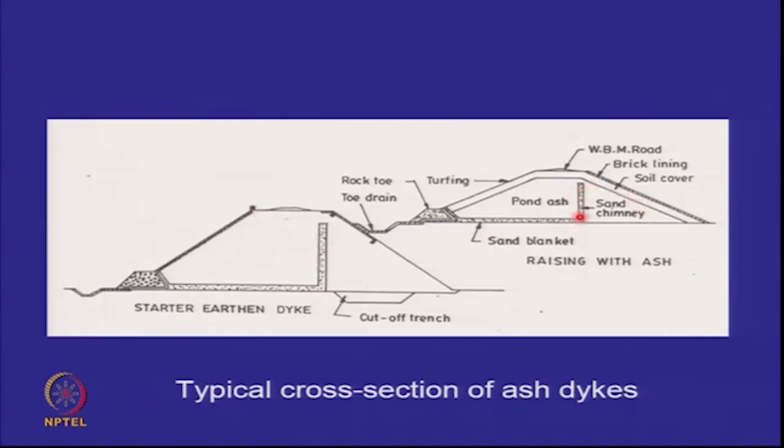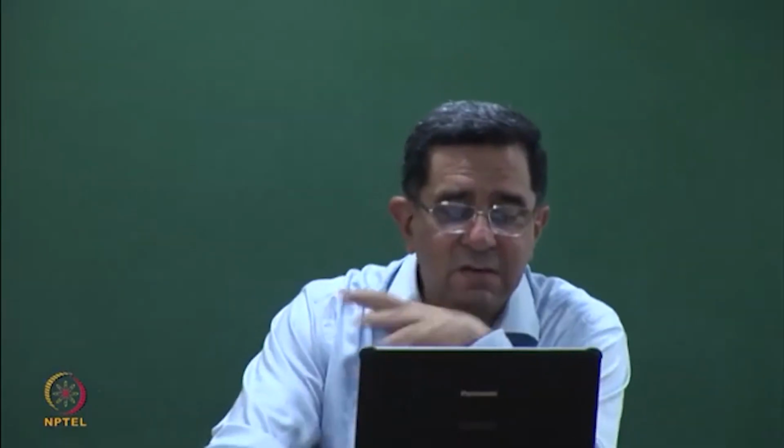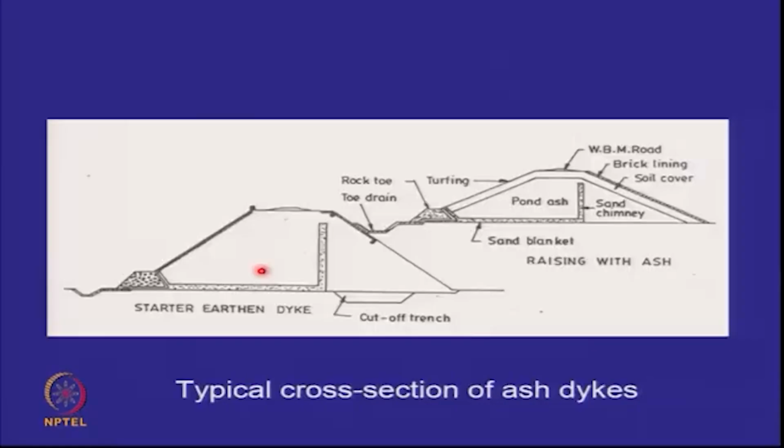And they are collecting the water of each stage in a toe drain and taking it away, right? So we are not allowing the water of this drain to come here, but if it overflows, it will come here. This water is collected in this drain, and in the lateral direction, the water is taken out by overflow. So that is the design which is used for upstream grading. Do remember that in any case, this ash has not been compacted. So you still have sometimes issues about this being very well made, but the failure surface going through soft ash or loose ash and giving you failure.